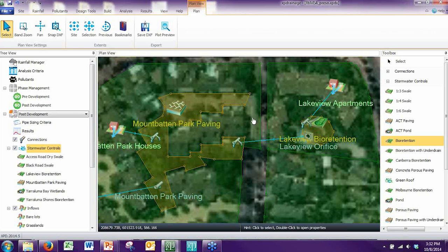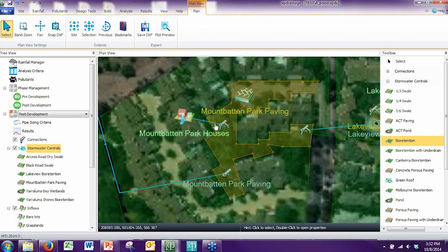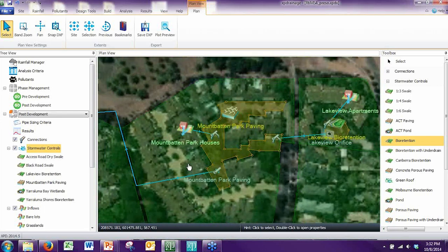So we kind of refer to the train, or the idea of them being strung together. This is a great example here, the permeable paving. So we have a portion of an area running across permeable paving, picked up in a curb inlet, and carried over to another part of the system. And so they string together in the system.